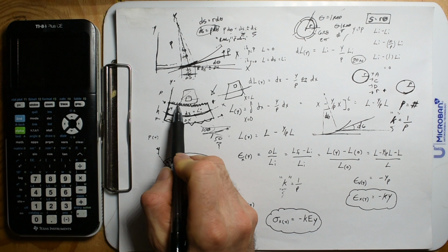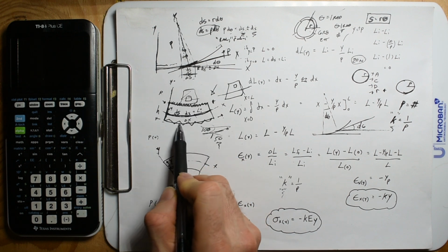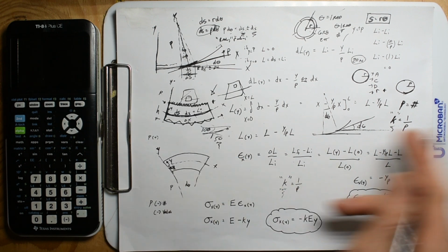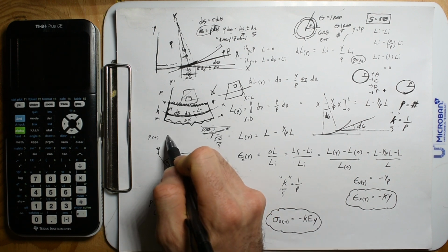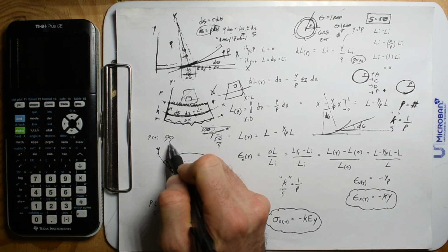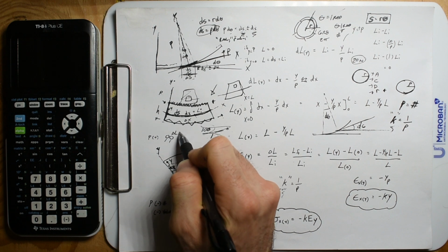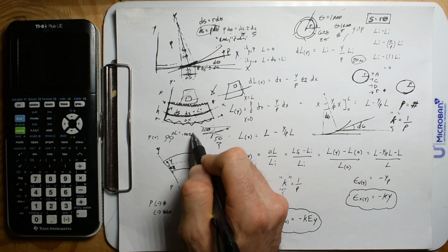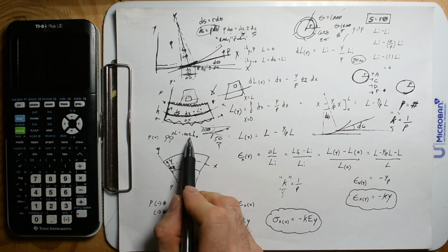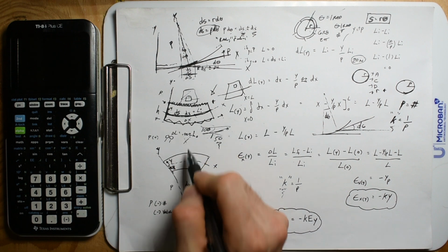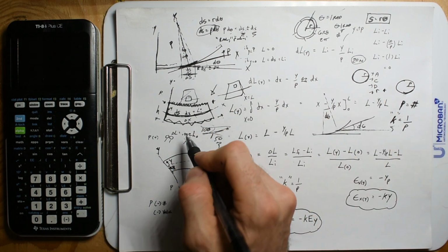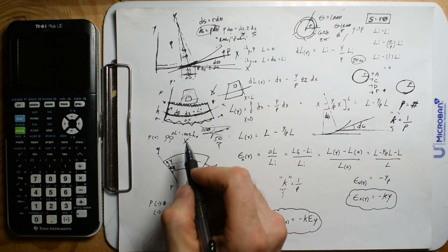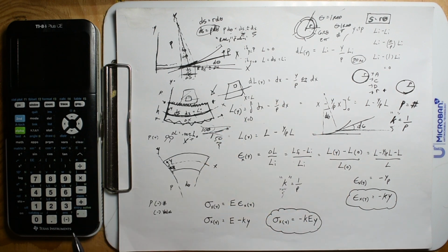These molecules get bunched up, and these molecules get stretched out. Now, in my intro video that I just made the other day, we have to keep in mind that these molecules can't stretch out more than a change in length of 0.002 times their original length. If we have that, we might have a failure of the beam, because it'll just keep stretching and breaking, so we have to keep within that limit.